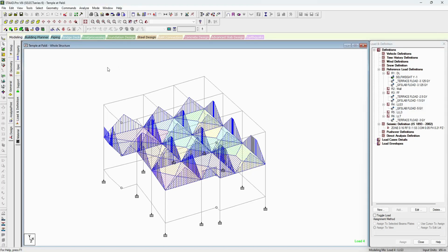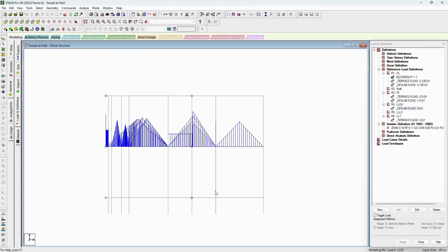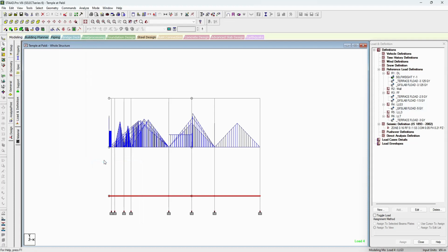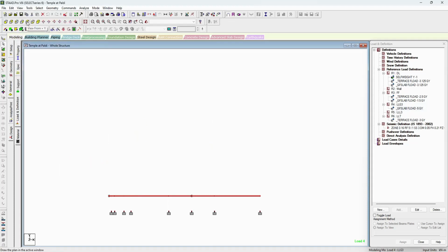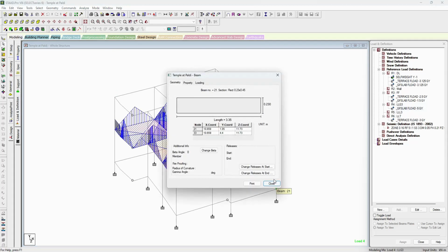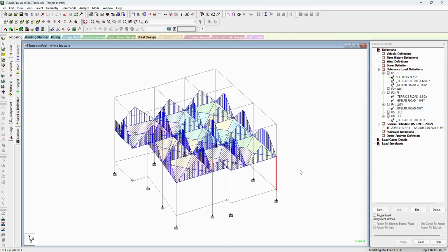Now the most important load, that is wall load. Let us select the first beams, select the specifications, and select the support so that we can know where the columns are. I have pressed Alt VV to show the selected beams only at the periphery. What shall be the height? 3.35, 11 feet. But I guess the beams I have modeled at plinth level should actually be at the pile top level. Yes, it shall be at the pile top level, right? So I'll have to revise the model.